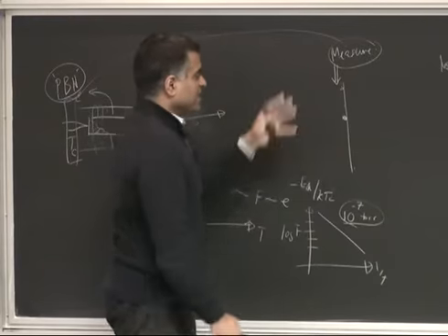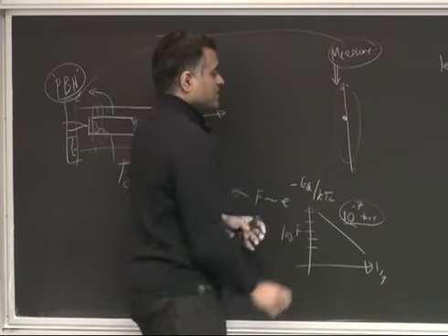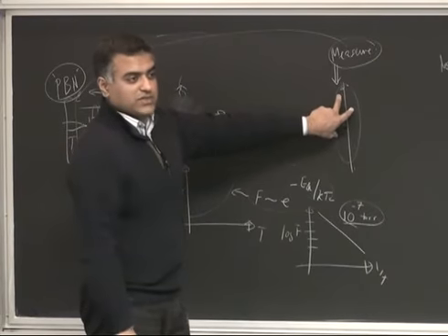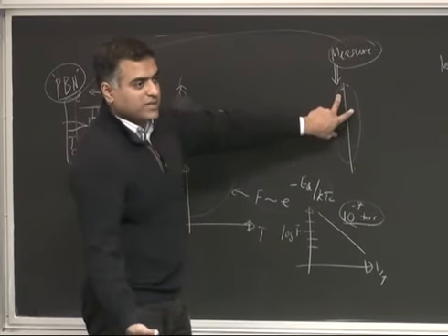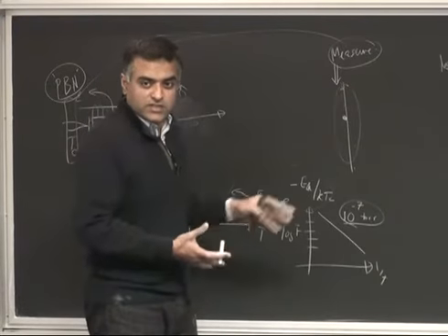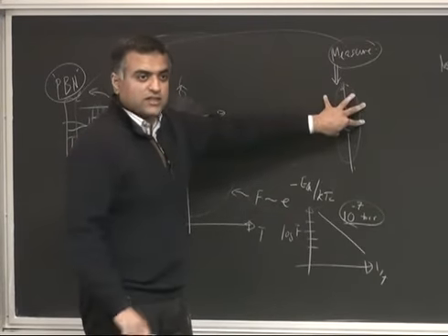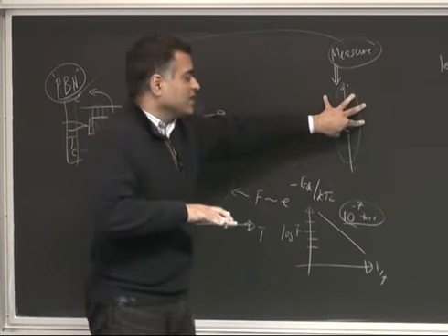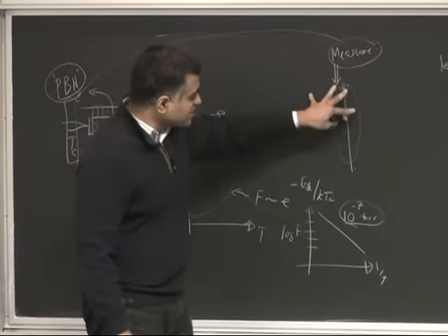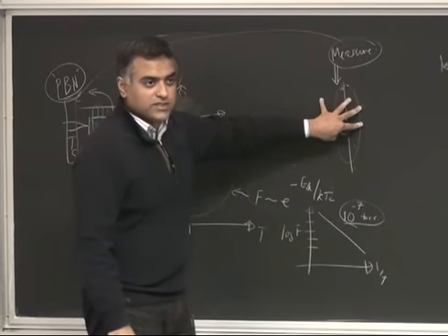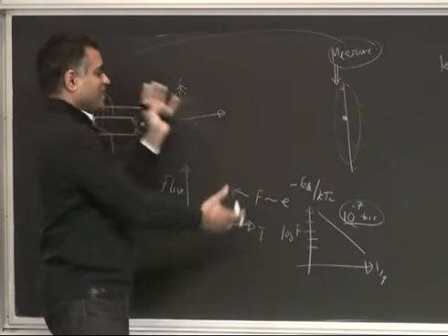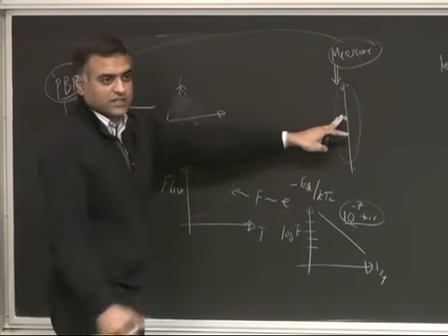Now what happens here is essentially some other things. You have to have a phase transition of molten gallium and arsenic, which are not chemically bonded, and you have to make them into a crystal. So there's a big phase transition going on here, quite a bit of thermodynamics, quite a bit of kinetics going on here. We'll cover those things as well. So this is a very precisely controlled phase transition, obviously, because you started with atoms in vacuum and you have a crystal now. So there's a phase transition somewhere there, right?